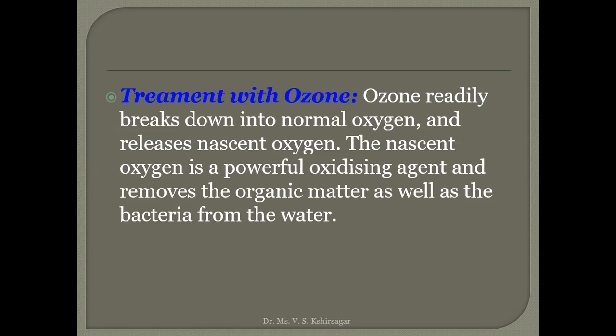We cannot buy ozone from somewhere and apply it wherever it is required. Wherever it is required, there itself, on site, it needs to be converted, and that extra setup needs to be added into the water treatment plant if you are using the ozonation method. Understood? So this is the drawback of the ozonation method. Only if we want a very specific type of treatment for the water can we use ozonation. Otherwise, in the public water supply system, it is not accepted.